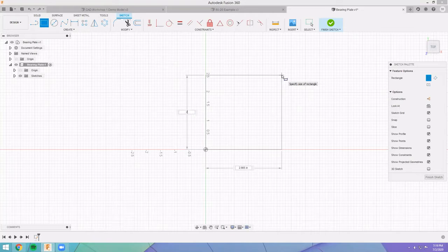So we're going to make this 2.5 inches tall and 1.75 inches wide. You might have noticed those little locks that appeared next to the numbers. Those locks appear as soon as you've typed something in and then press tab to get out of that field. The lock is basically the same thing as saying this dimension is going to be constrained. So instead of clicking D, dragging that thing over, double clicking it, changing the value, clicking enter, you can just type it in here and you get the same end result.